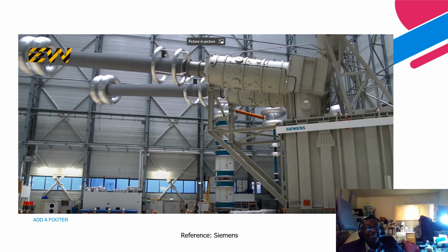So just imagine you are utilizing 3 of these. And like I made mention, the length is about half of a 100 meters track field. So in the middle of 100 meters, that's how these transformers can measure. So this is the bushings, how it looks like. And because of the high voltage, you utilize a corona ring or graded ring. This helps to basically reduce the stresses that is around the terminal over here.